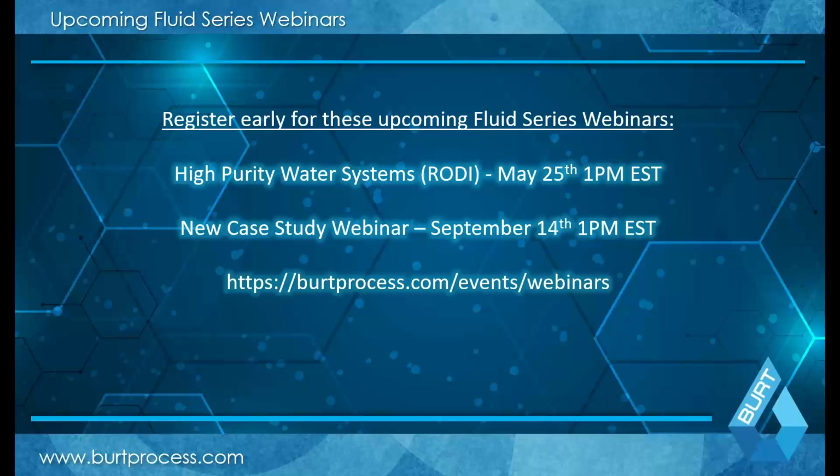It's going to be recirculated back now under some flow rate, 30, 50, 100 GPM, depending upon what your system flow rate is. They don't have to be corresponding, obviously, but they do have to be somewhat proportional, and then that's being educted right back into your mixer backwash. Now you're basically blasting this larger volume of charged reagent waste right into your mixer backwash, and that creates a lot of efficiency when it comes to your pH treatment in those cases, as opposed to just simply dripping into the tank.